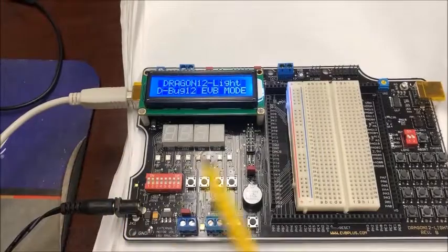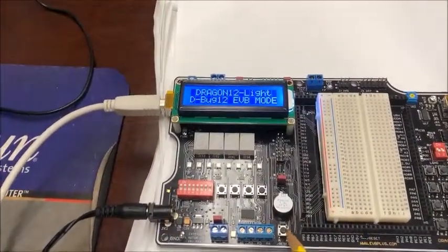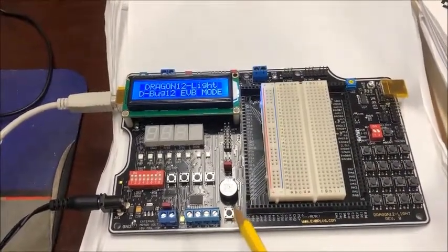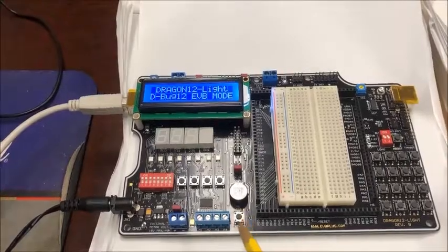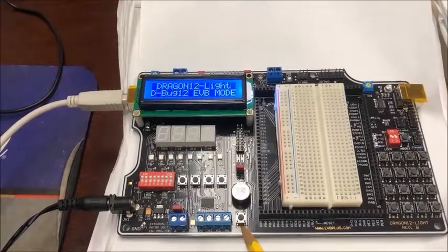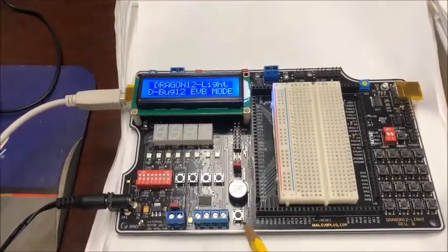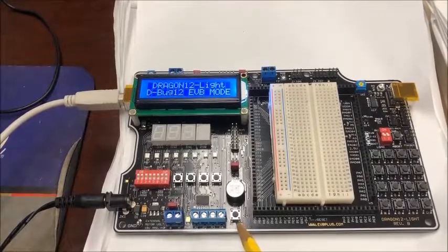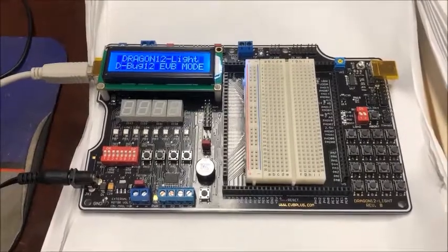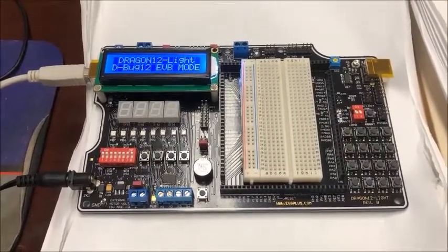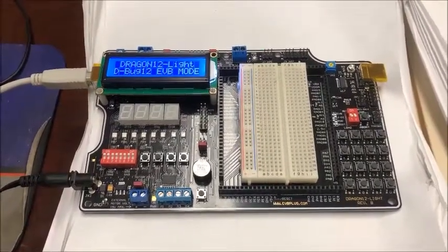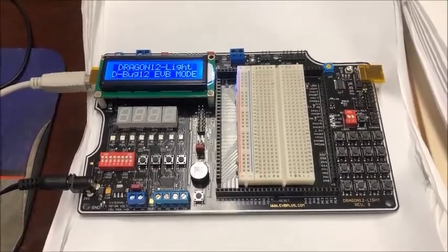Second, this is the reset button. The reset button is important because we will use this push button switch when we want to download a program to the board. So it is written here, reset. This is the reset button switch. Next we will go to the software and do the steps for downloading an S19 downloadable file to this Dragon 12 board.